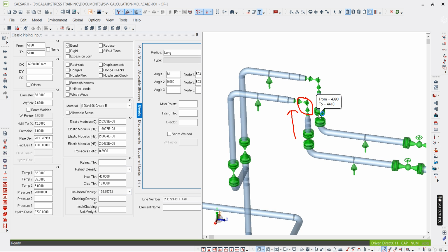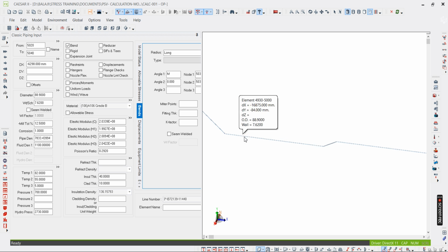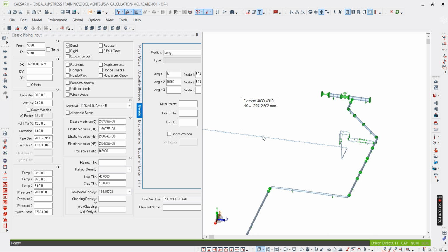That is safety valve set pressure. So what happens means here this will pop up, this will open up. This PSV will open up and pressure will be released here, and the fluid will move here and it will be collected to the pit. So in this case it is collected to the pit. So this may be considered as a closed system.